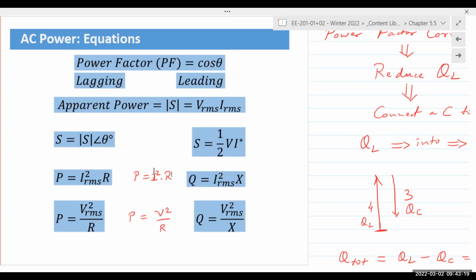Note when you use these quantities, right? Q by itself and X by itself does not have J. It does not have the imaginary number. It's just talking about that component, reactive power and reactance. It's when you take the reactance and plug it into the equation for impedance, you have JX, JXL, JXC.